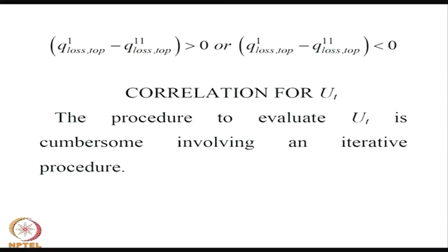So, this is a sort of involved calculation, and it requires iterations unless you know the guessed values. On top of it, most of the time H p C 1 and H C 1 C 2 are the free convective heat transfer coefficients, which themselves will depend upon the temperatures.